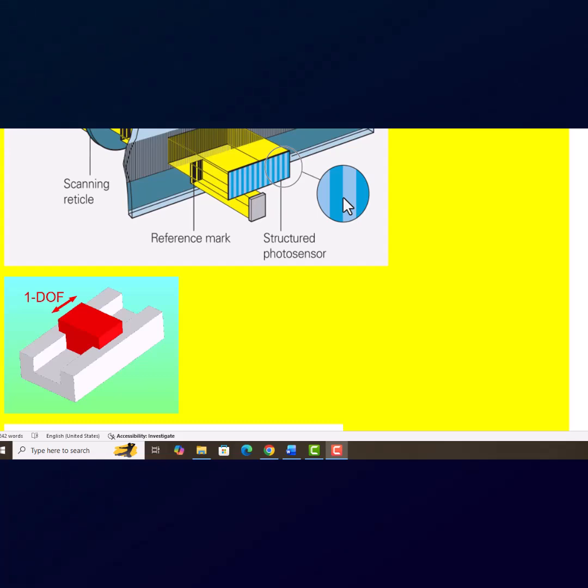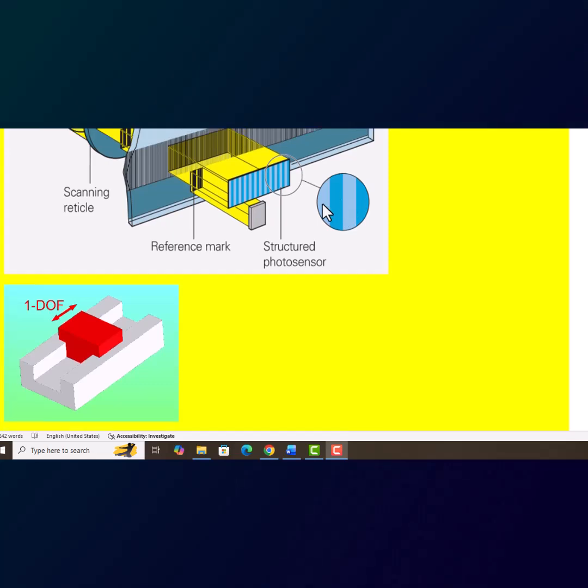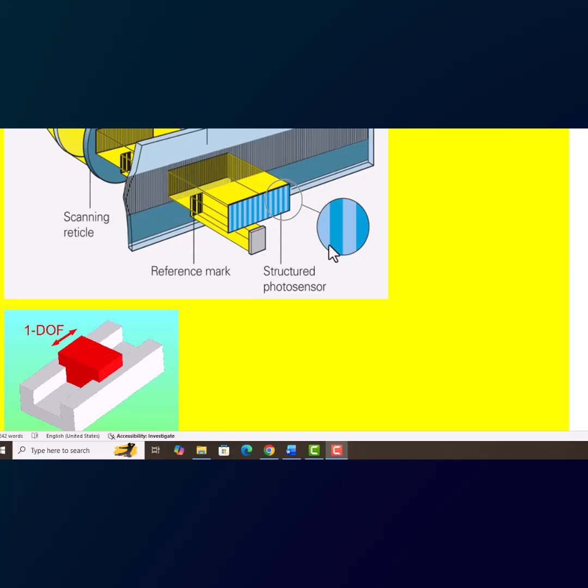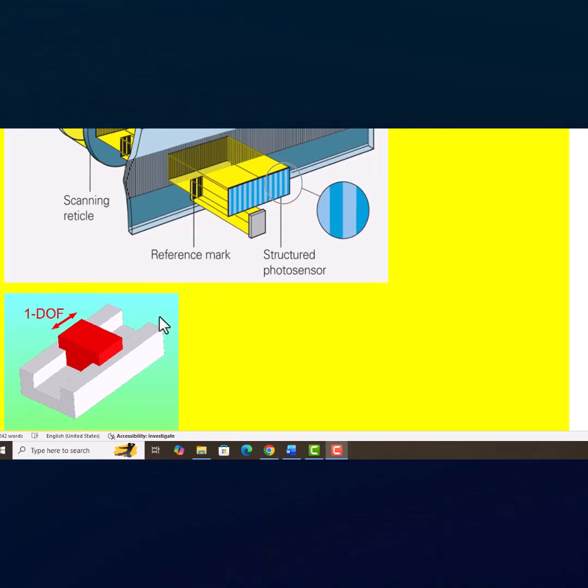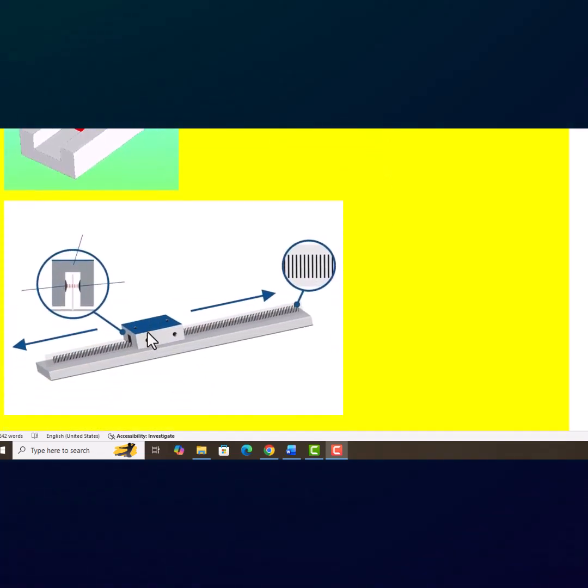Based on the number of pulses produced by phase A and phase B, the distance traveled by the prismatic joint can be determined, and if the number of pulses produced and the time taken are known, then the velocity of the movement can also be calculated. And based on the phase difference between the pulses produced by phase A photodiodes and similarly phase B diodes, the direction of the movement of the linear joint with respect to the reference point can be decided, as I discussed earlier.